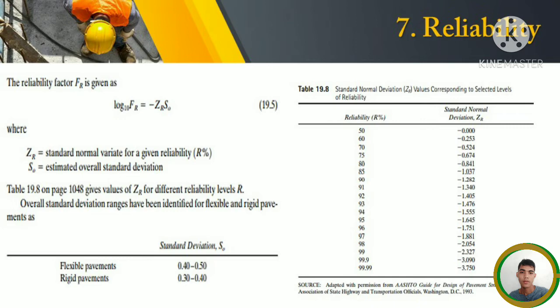Reliability design levels, in percent, which determine the assurance level that the pavement section designed using the procedure will survive for its design period, have been developed for different types of highway. For example, a 50% reliability design level implies a 50% chance for successful pavement performance. That is, the probability of design performance success is 50%.